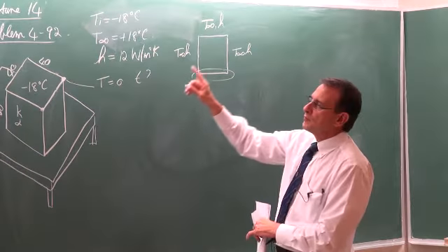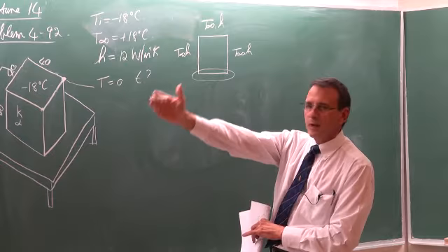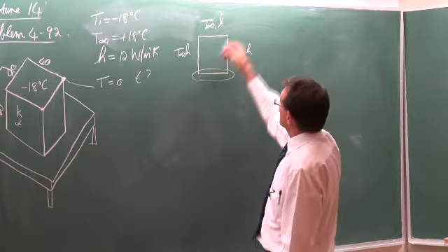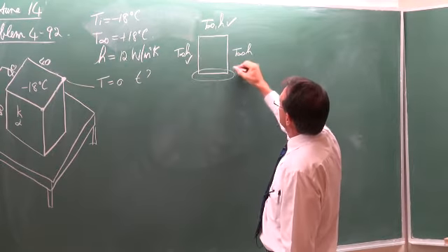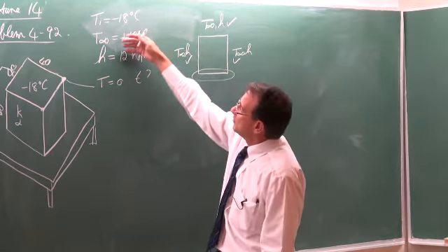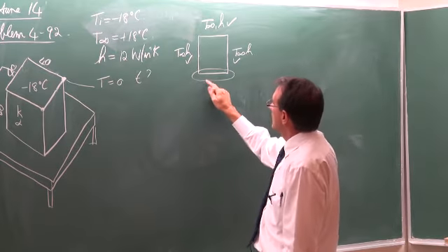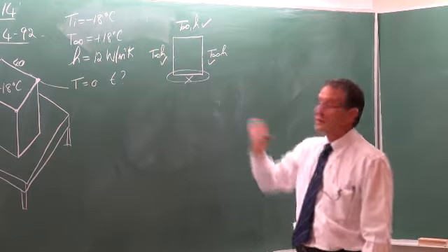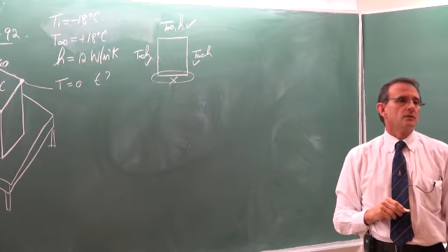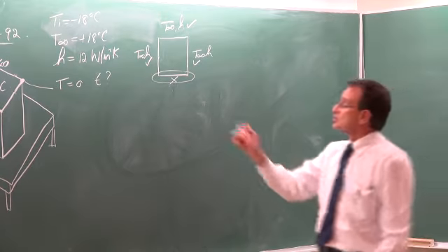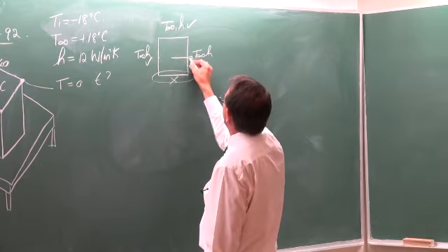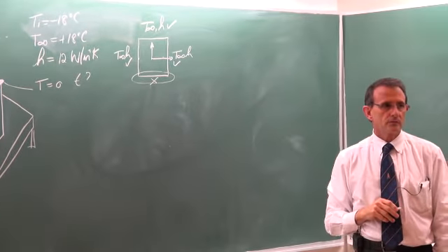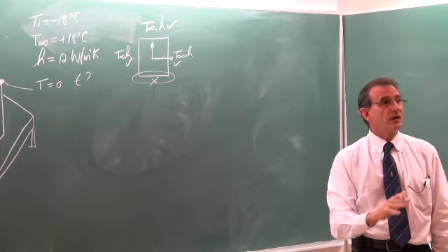Okay. So if you think back in terms of the mathematics that we've done with the principle of superposition, one of the requirements was that the boundary conditions in terms of the environment temperature and the heat transfer coefficient must be valid on all the surfaces. And it is not valid on that surface there. So you cannot just start using the equations as given in the textbook. Okay. But we can fix it.